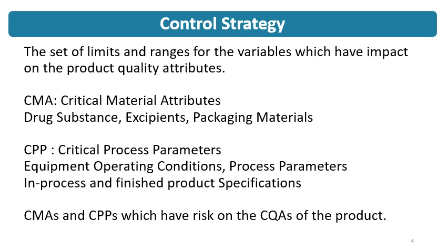Equipment operating conditions involves the important parameters like the occupancies, the design of the equipments, the processing times, the speed of the machines, and the critical process parameters like for example the machine speed in compression machine, inlet air temperature for drying for the FBP machine or FBD machine, and there are many more depending on the unit operations involved in the manufacturing of the formulation.